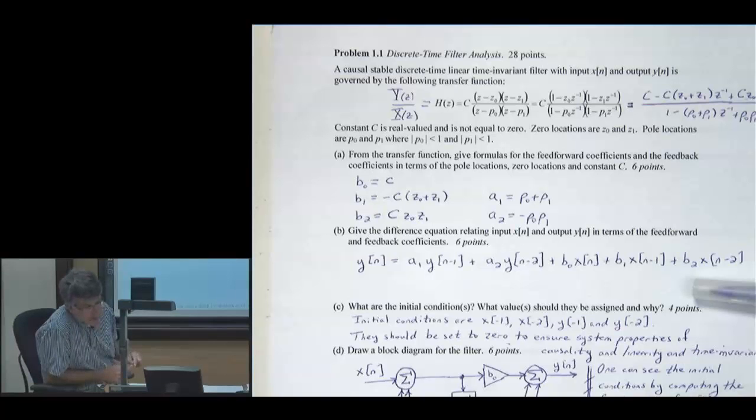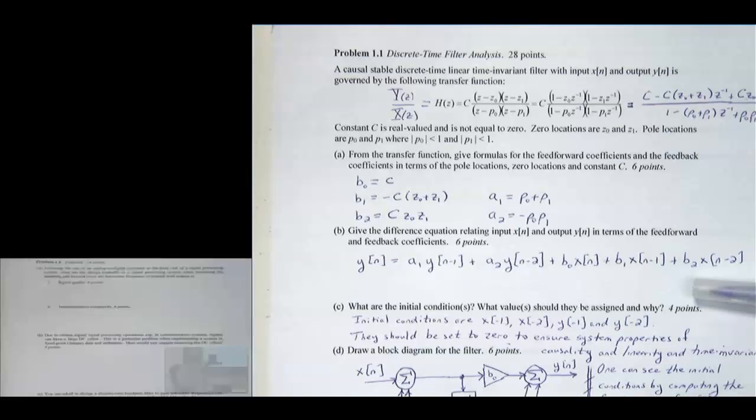Assume the use of an A to D converter at the front end of a signal processing system. What are the design trade-offs in a signal processing system when increasing the sampling rate beyond twice the maximum frequency of interest? There are two impacts here: a trade-off between signal quality and implementation complexity. So who wants to argue what happens to signal quality? You can argue this all kinds of ways.